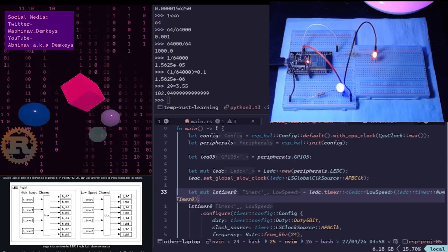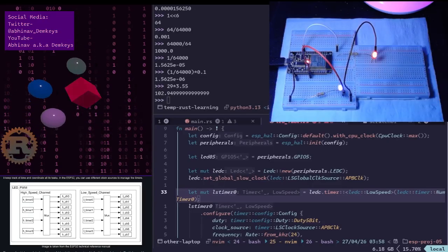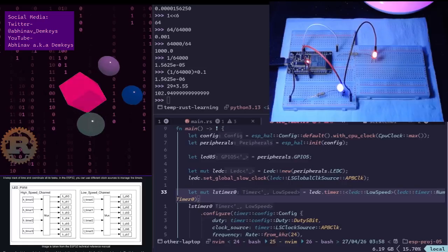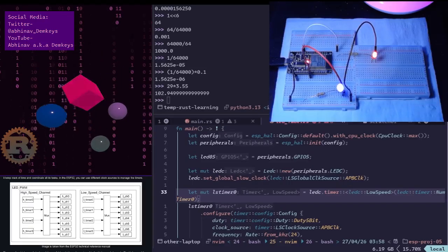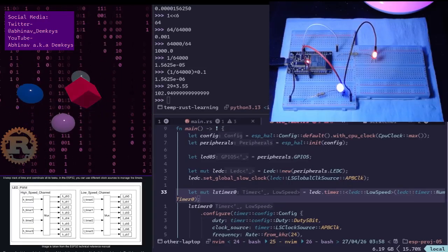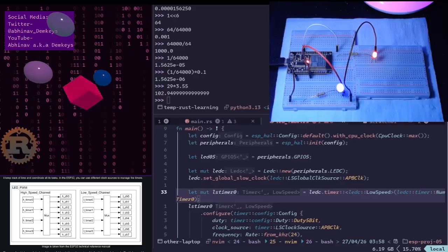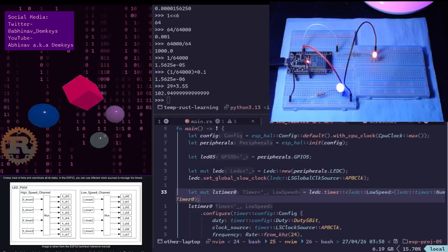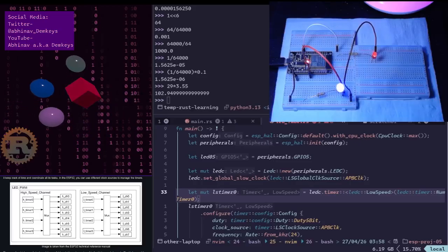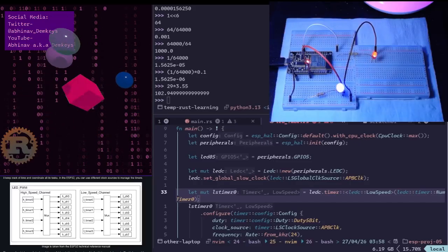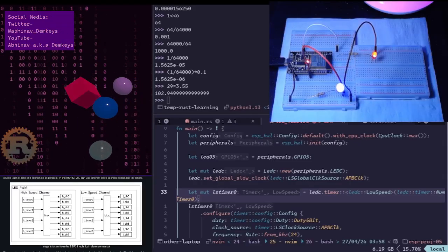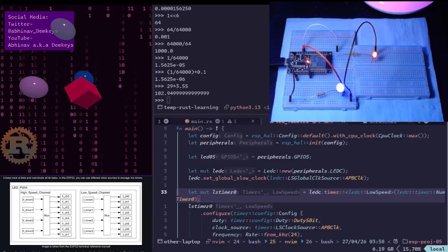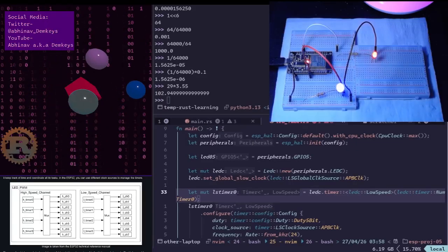Sorry, zoned out. Okay, it decides where the entire LEDC peripheral gets its raw material, quote unquote, or the clock signal from. Impact: if you change this, every single low speed timer, that answers my question. If you change this, then every single low speed timer and channel is affected. You are essentially turning on the main pipe for the whole system.